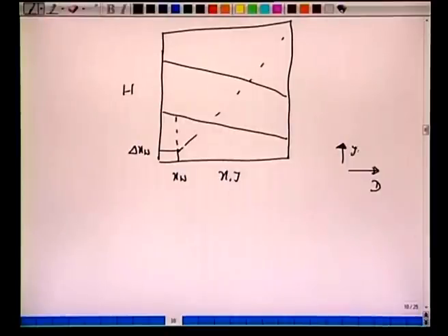And here we said that this is Y Np plus 1, H Np plus 1. So this plate is Np because this boiler acts as a theoretical plate. All right, so if we start from here, we must note that this Xb, let's correct this to Xb, bottom product, or W, we had XW, and we had this HW. So these two streams are in equilibrium.